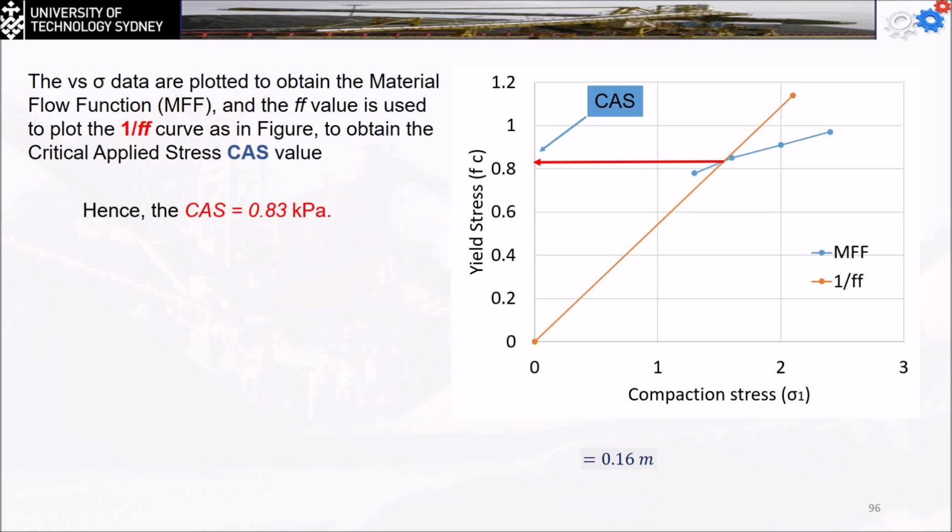Now, do you recall the equation for the B minimum, which is the minimum diameter we should have? Now, we got the theta as 28. Now, we said in practical life, I should use 3 degrees less than the value I got. So it should be 25 degrees. But I'm going to keep the 28 in this example because I don't want to confuse you.